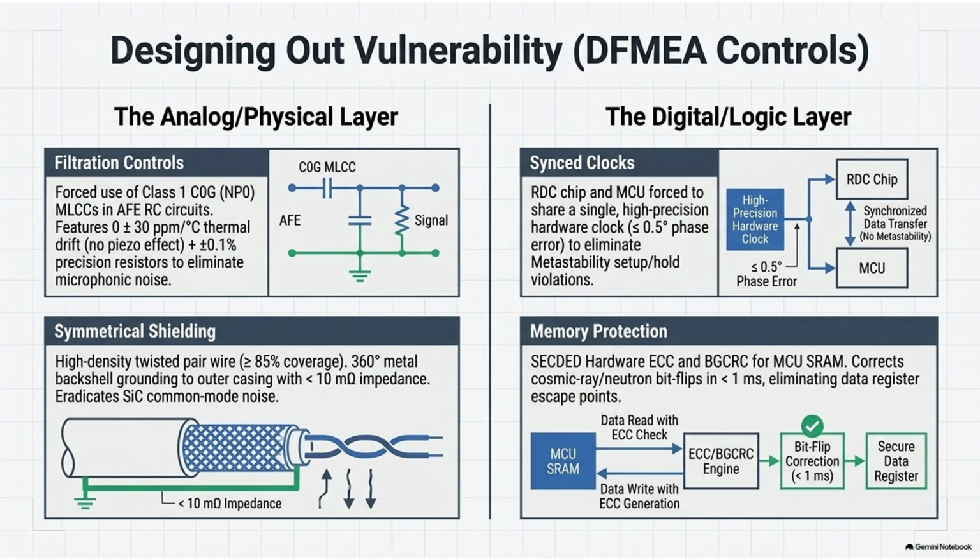As the die compresses the metal terminal around the wire, the sensors plot a physical force curve in real time, mapping exactly how much force is required at every millimeter of the stroke. It is utilizing Hooke's law and the plastic deformation properties of the metal. Right. Every specific terminal and wire combination has an ideal force displacement signature. And if the curve deviates by a fraction of a percent, meaning maybe a single strand of copper wire is missing or the insulation wasn't stripped back far enough, the press immediately halts.